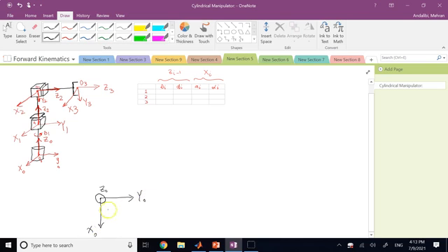And then, parallel to the right along the z, if you move for this distance, which is from O0 to O1, I call it A or A1. So A1 is the length from here to here. You go up, so you cannot see it because it's perpendicular to the board, but then you have to rotate for X1 and Y1, so your frame X1, Y1 looks like this. So this Z0 is also the same as Z1. Correct, let me make sure. This is Z1, I have to avoid typos. So this is also the same as Z1, and then here is Y1, and here is X1, and this angle is theta 1.